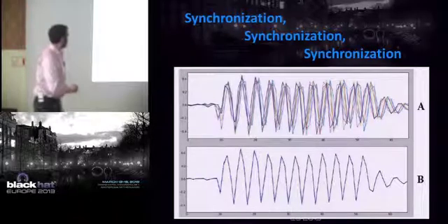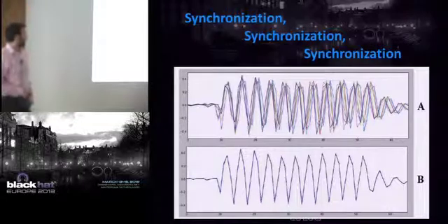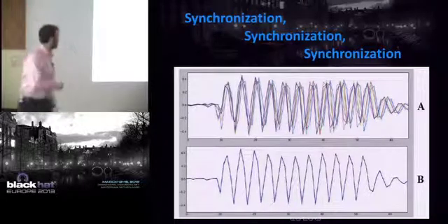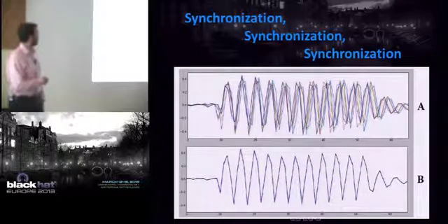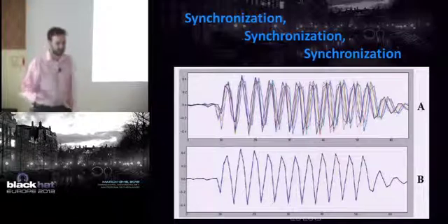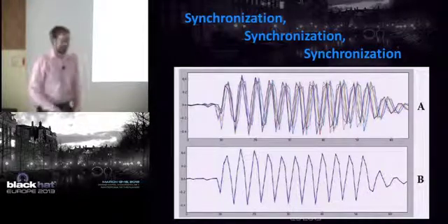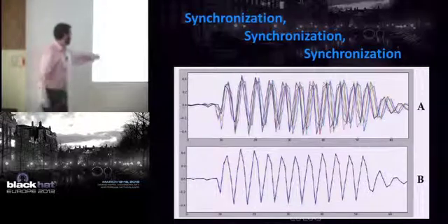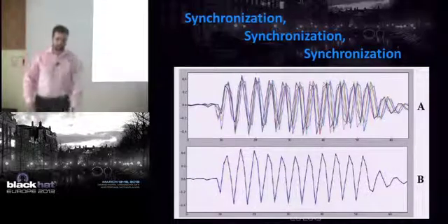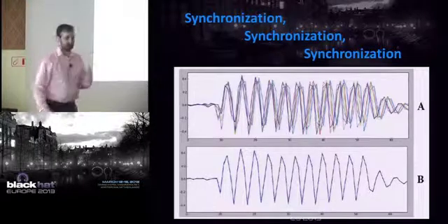In B, I'm sampling at about that same speed, 96 megasamples, but I've perfectly synchronized the clock to the device. In both cases, I have 10 traces overlaid. In A, you can see that's garbage effectively. They're not lining up at all. In B, these 10 traces are perfectly lining up, and you can only barely see in a few spots where they differ. And again, it's the exact same hardware, running 10 operations on the same data.